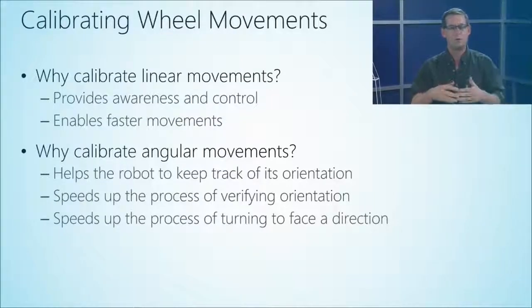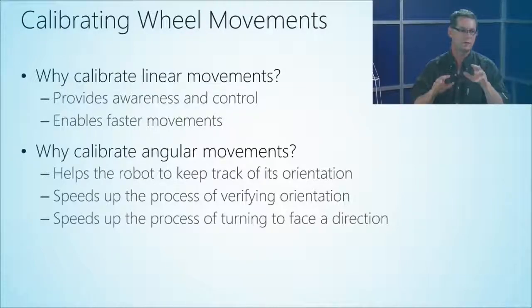So if we're moving around in the area or mapping an area, we don't want to move a little bit, take a reading, see where we are, because we need to maintain our reference. But we can't just move big, long distances and then hope to find our reference point. You have to move incrementally, but doing that takes so much time. So what we want is to move a calibrated distance using our motors, a known amount. Then we don't have to make so many small moves and recheck our sensors. That's one of the things that makes it so important.